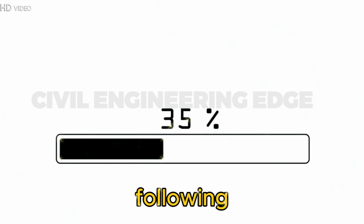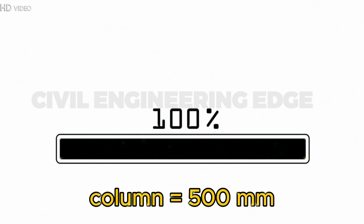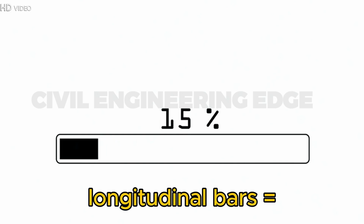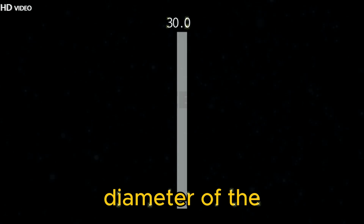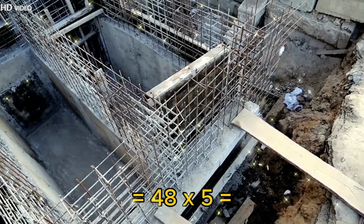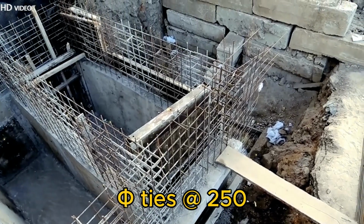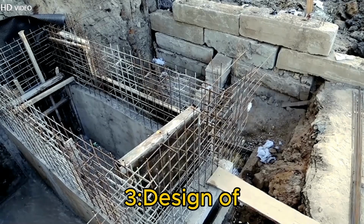Least lateral dimension of the column equals 500 millimeters. 16 times the diameter of the longitudinal bars equals 16 by 20 equals 320 millimeters. 48 times the diameter of the ties equals 48 by 6 equals 288 millimeters. Provide 6 millimeters phi ties at 250 millimeters c/c.